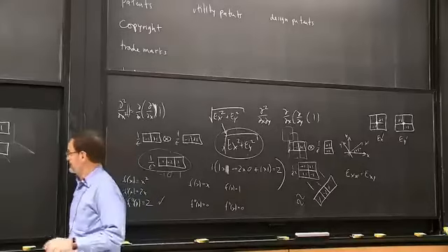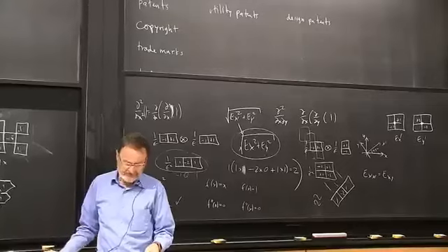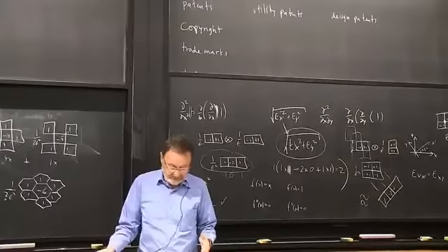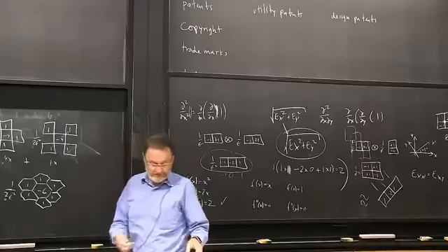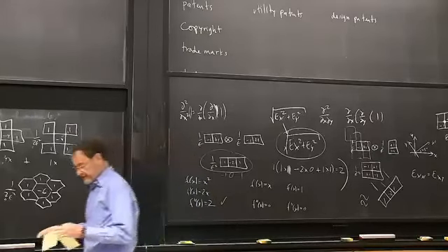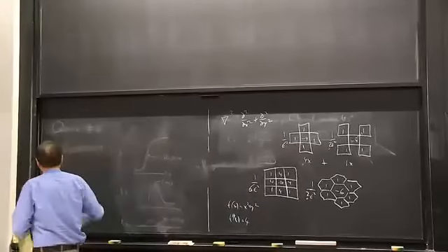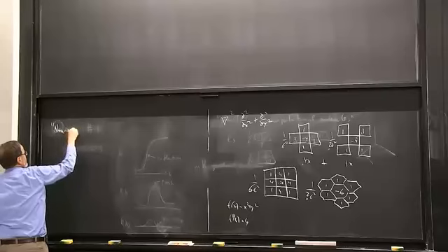Okay. So that was the front end. And this has to be very efficient because it's run on every pixel. And it also lends itself to special purpose hardware, of course. So the next step was our sub-pixel edge detection method. So we used what is called non-maximum suppression.